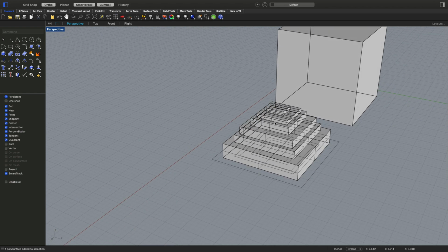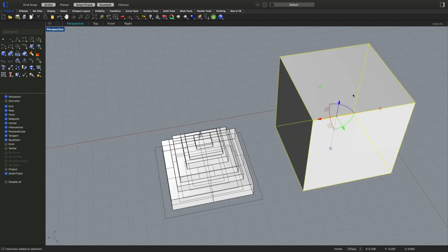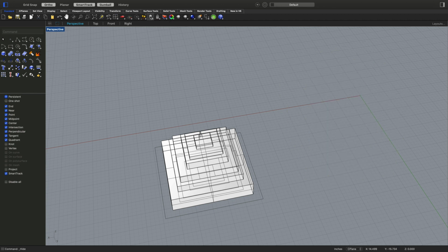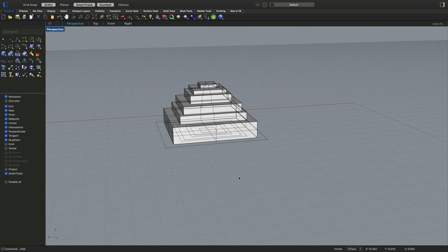And this I could insert into this and subtract out on all sides, but I'm going to make it a little bit more complicated than that. So I'm going to hide this block. Just click on my light bulb here, or it might be on the tool sets over here if you've got a Mac, or if you've got a different version of Rhino, or just type hide.